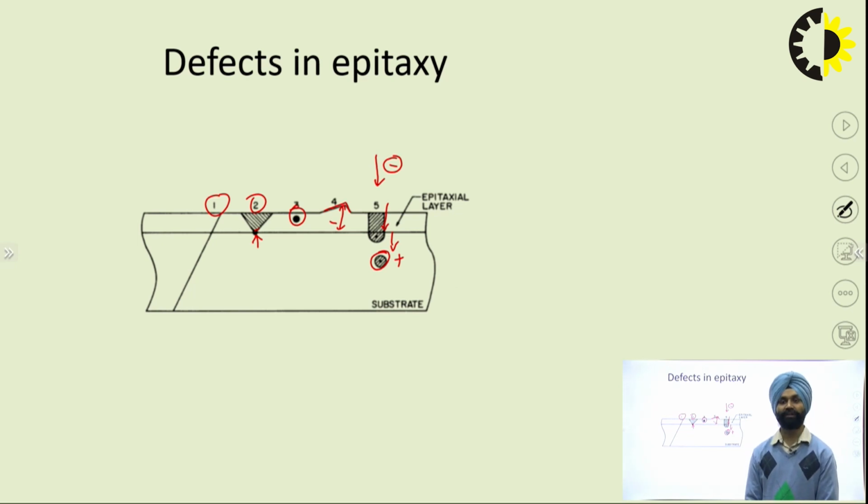We have also discussed the buried layers and the reduction of the buried layers. Mainly the reduction of these defects is by higher temperature with higher mobility and lower pressure. So we prefer LPCVD, which we have discussed in the main lecture also.